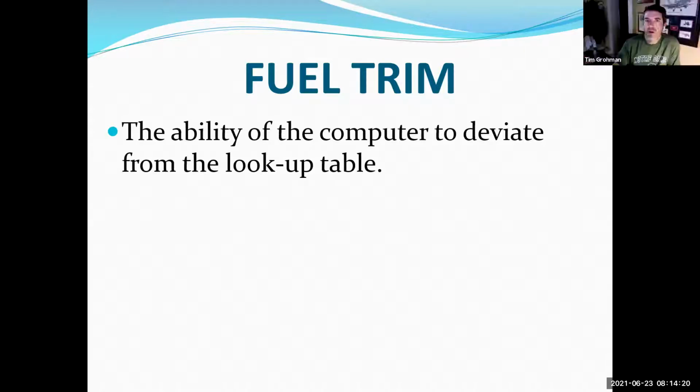Are you talking though, Brian, in this case, you would look at the low-hanging fruit things first, the mass airflow sensors, those kinds of things, and then when you don't see any other problems, that's when you start going down that hole of, okay, the on time is longer or whatever. Yeah, exactly. I mean, 80% of the time, if I have a fuel trim code at idle, it's a vacuum leak on a mass airflow sensor car. It just is.